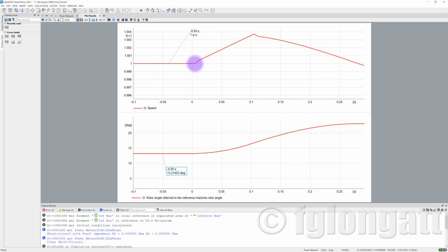During the short circuit, you can see this is, let me use my big pointer, okay? You can see over here, this is the rotational speed. The rotational speed starts from the synchronous speed, 1.0 per unit, and the machine starts to speed up, speed up, speed up. And here, this is the moment where the short circuit is clear. When you disconnect the short circuit, now the machine has the possibility to deliver active power to the network. And that is the moment that the machine tries to reach stability. That is the moment where the rotor tries to regain an equilibrium point and to reach stability.